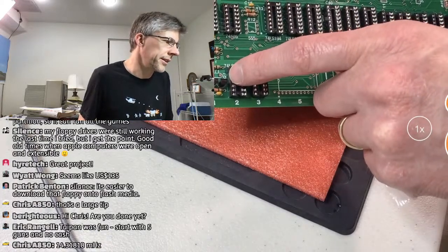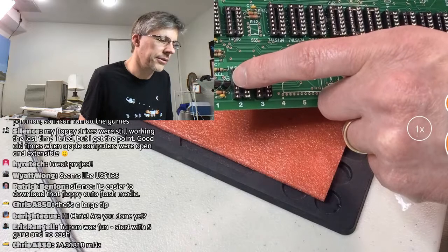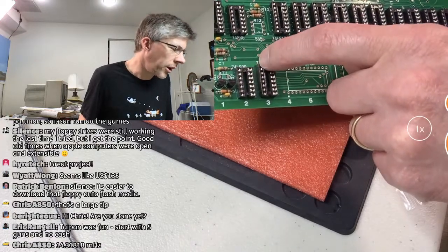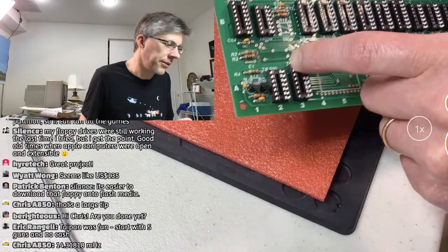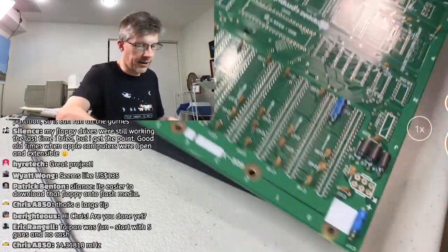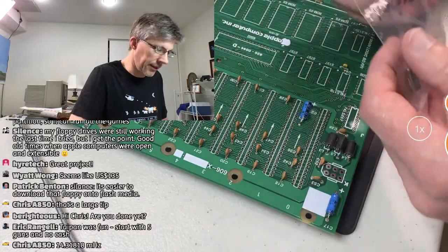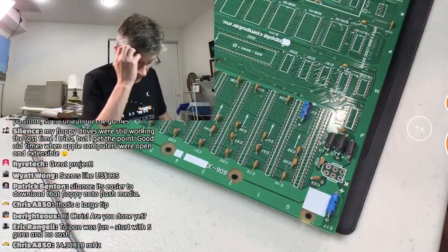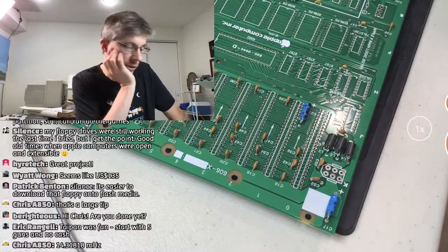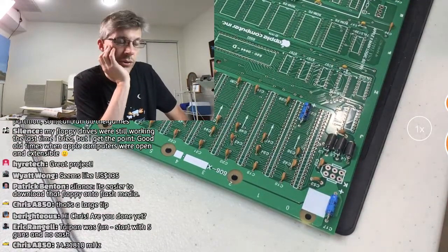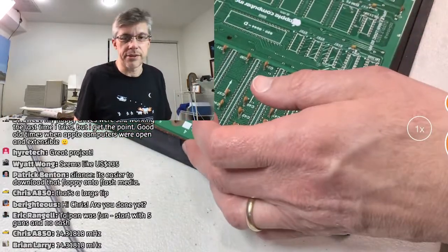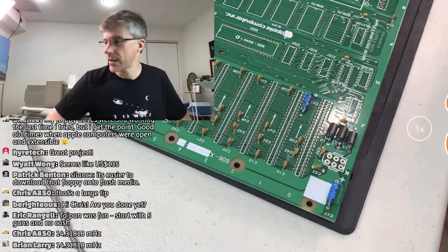So for example, it's split in half, and then the 7 megahertz goes to the video, and it gets split down into a 1 megahertz signal, which goes into the 6502 chip. And then the rest of the board can use it, and that clock signal also goes to all of the sockets too. So if you have a peripheral card, that signal is available on those sockets as well.